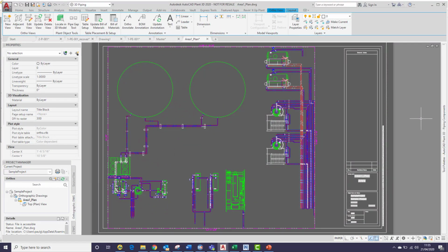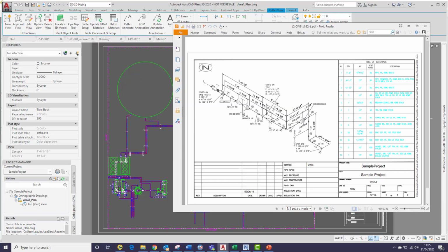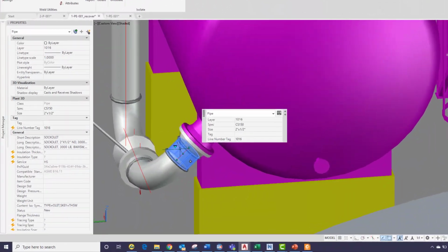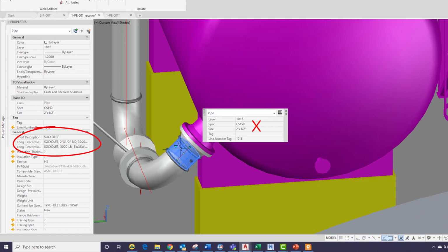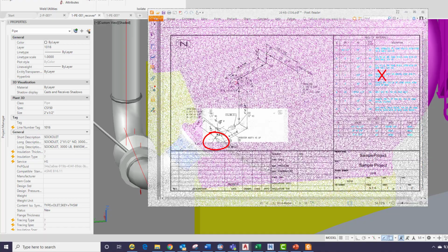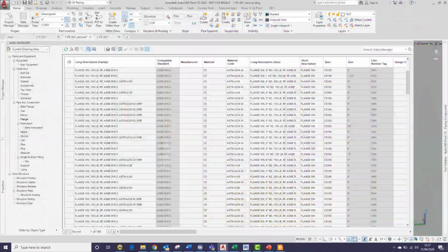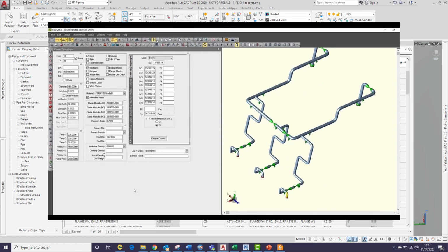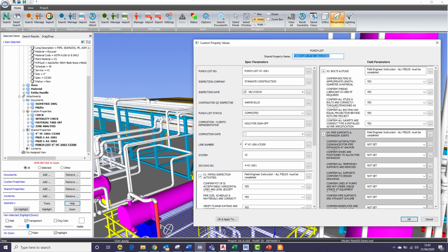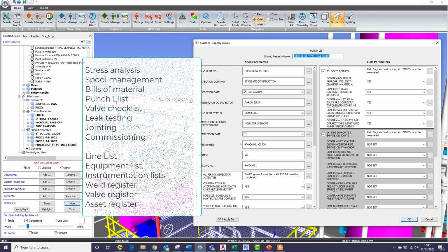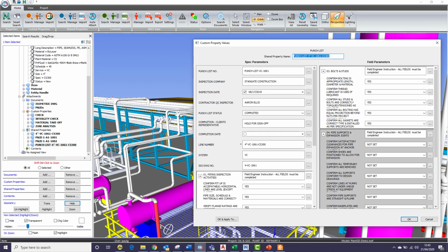Unlike in the days of manual production, where a certain amount of draftsman's license was acceptable, it's essential that the underlying model attributes are correct. Otherwise, any mistakes and omissions will filter through to the automated ISOs and wreak havoc with our bills of material. And because our models can be used via other software applications later on to drive various analytic and operations processes, it's essential that the basic information is validated as far as possible.